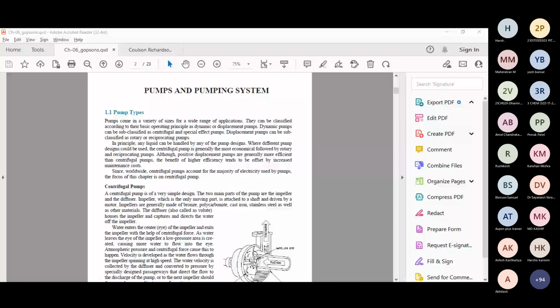Now that electrical energy is converted into rotational energy and conveyed to the pump shaft. Between the shaft of the motor and the shaft of the pump, there is some loss of energy because of the coupling. There can be something like 3 to 5% loss because of the coupling, right? If there is misalignment, if your setting is not proper, that is one of the losses because of coupling. Now the energy which reaches the shaft basically boosts the fluid velocity.